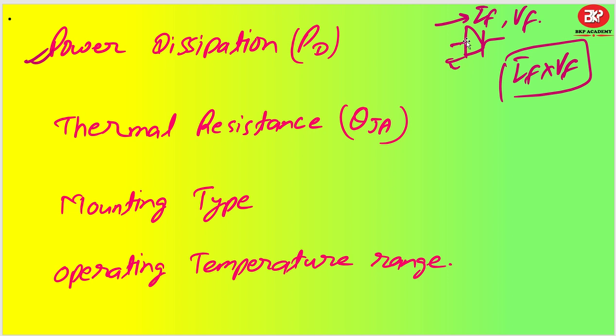So as you can see, as you go ahead with a little bit higher amount of current, your power dissipation will increase. So based on your requirement, you have to understand whether it is 50 milliwatt capacity or 1 watt capacity, or like 10 watt capacity. So what is your circuit demanding? Based on that capacity you will be choosing a power dissipation of your diode. Okay. And power dissipation capacity also depends on the package size, whether it is bigger package size or smaller package size, that we will talk about in very detailed fashion now.